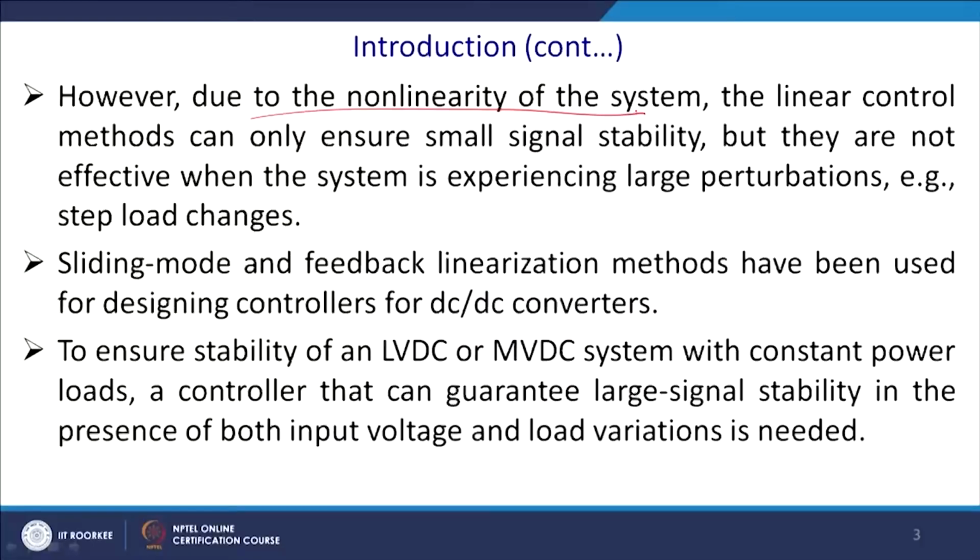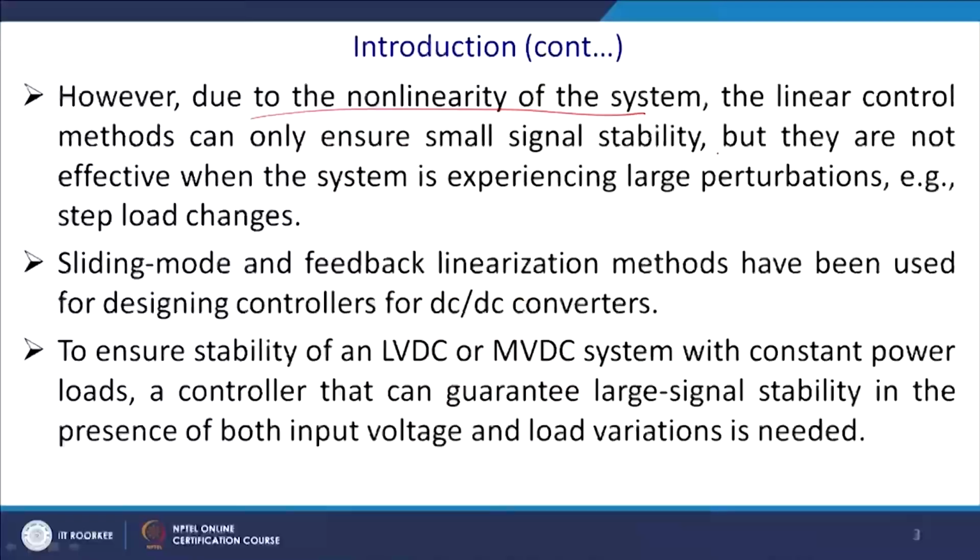However, due to the nonlinearity of this system, these linear control methods can only ensure small signal stability. If there is a large change, the equilibrium point itself changes, and thus you cannot apply small signal analysis techniques to analyze stability for a large signal change. They are not effective when the system is experiencing a large perturbation. For example,